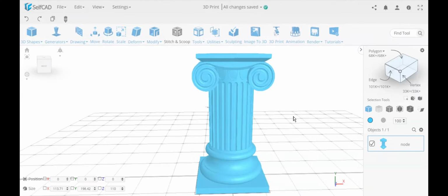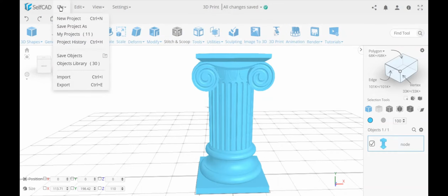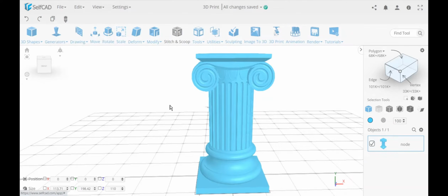When it comes to CAD formats, you have different CAD formats. Actually, each software has its own custom format, and they're not interchangeable, but there's a format called STEP file, which allows you to exchange between CAD software. It will not transfer over parametric data, but it will transfer over the basic geometry. And if you go to the import section in SelfCAD, you can actually import STEP files as well.